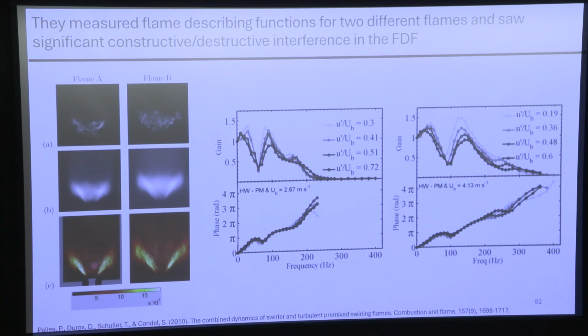And this is what has been processed using something called the Abel convolution, which basically, if you assume axisymmetry, kind of looks like what the plane in the middle would look like. You can tell when images have had it applied because you get this weird artifact along the center line if your data isn't perfectly axisymmetric, and no swirling flow is ever axisymmetric.